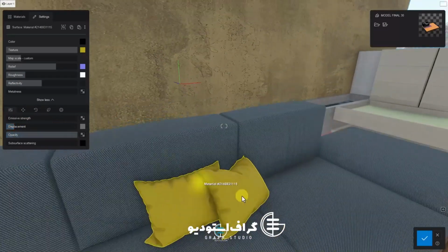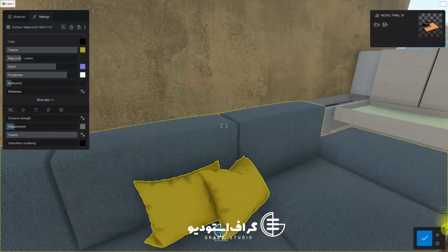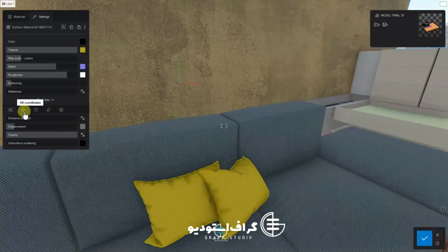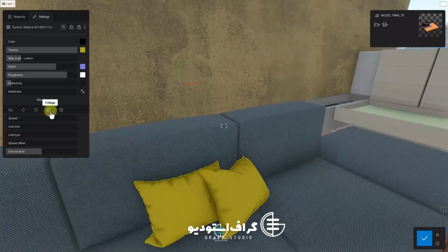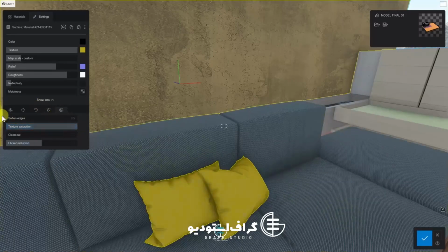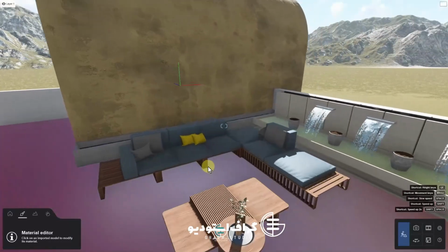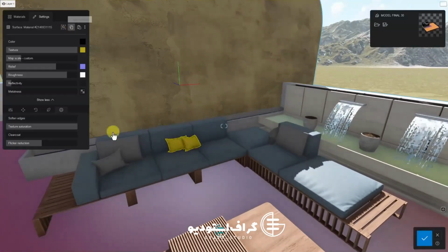Now guys, Photoshop is suitable for creating the normal map, but displacement can be created in more specialized software, like Substance Designer, or even the simplest method we used last time, which is shader map software. You drop a diffuse map there, and it automatically creates the height map, and the result is shown in real time. You can easily learn that too. I'll teach it when the time comes.